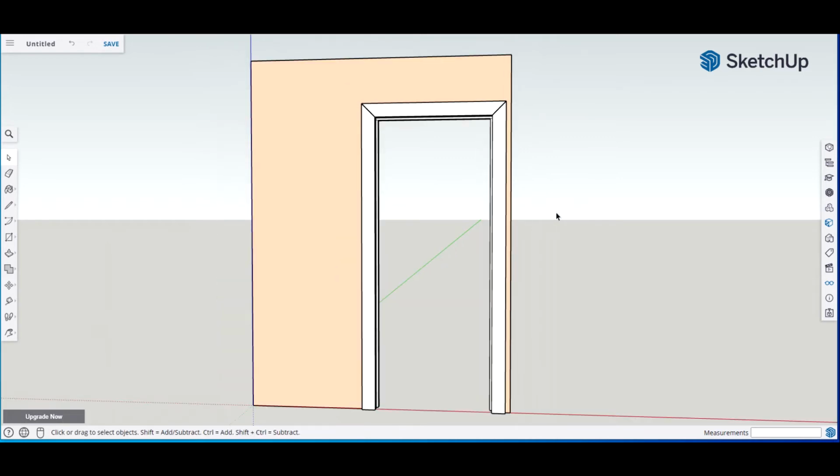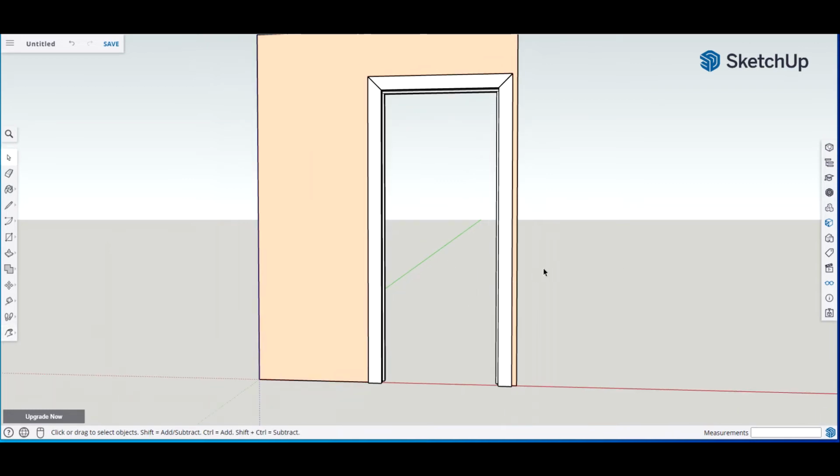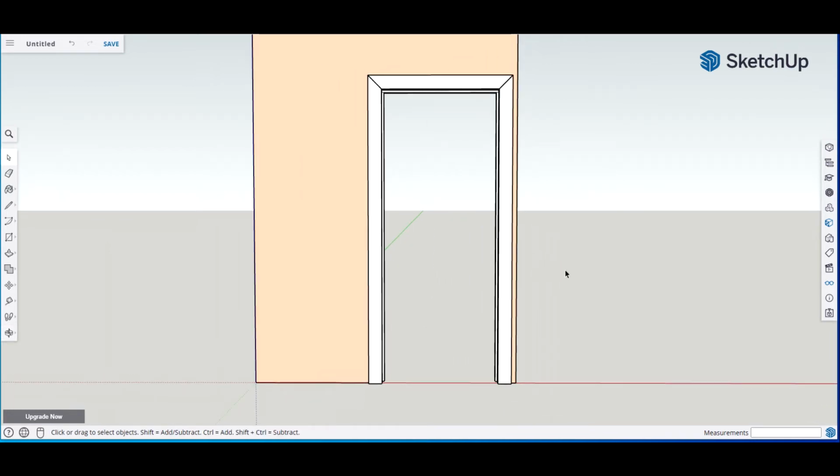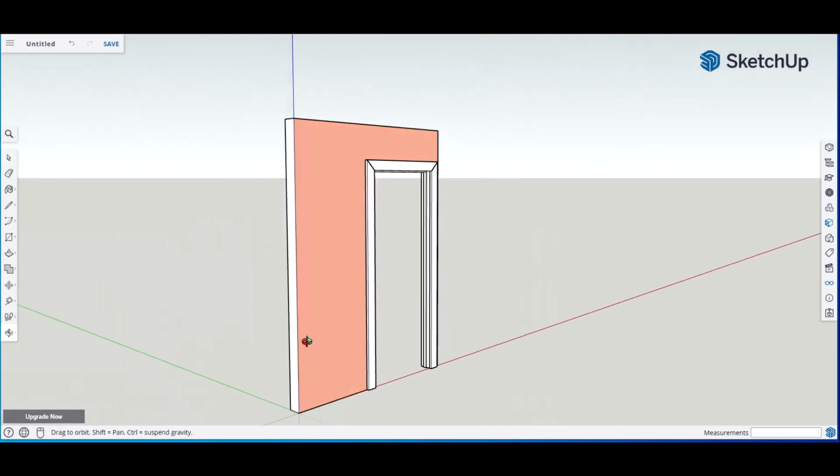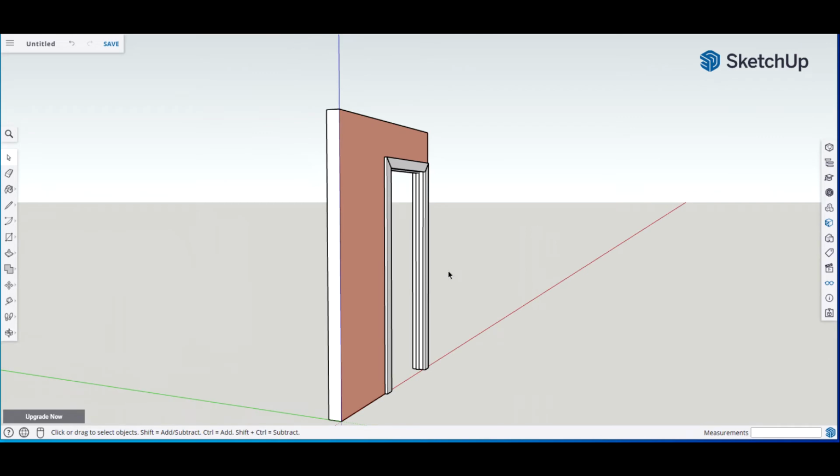Let's create some base molding, and I'm not going to do fancy base mold. It's just going to be a placeholder to know how thick everything is, so we can take some measurements and see how far off the wall the barn door needs to be. So the first step is to add some more features to this wall here, because in my hallway I have a little bit of wall sticking out about 3.5 inches here, and same thing on here. So we're going to draw that, and we're going to do it from here. We're going to do R, come up here. Now we want to be on the red, so let's just bring it over. And if you have trouble getting on the red, right arrow key, bring it down.